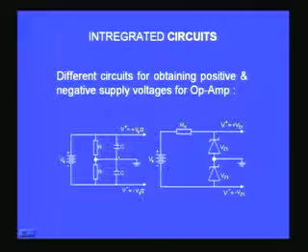I can have additionally some capacitors here, so that takes care of any transients. So when I have such an RC combination connected in parallel and the center connected to ground, I can have plus Vs by 2 and minus Vs by 2 corresponding to the Vs that I use, and this can be used in our operational amplifier circuits.